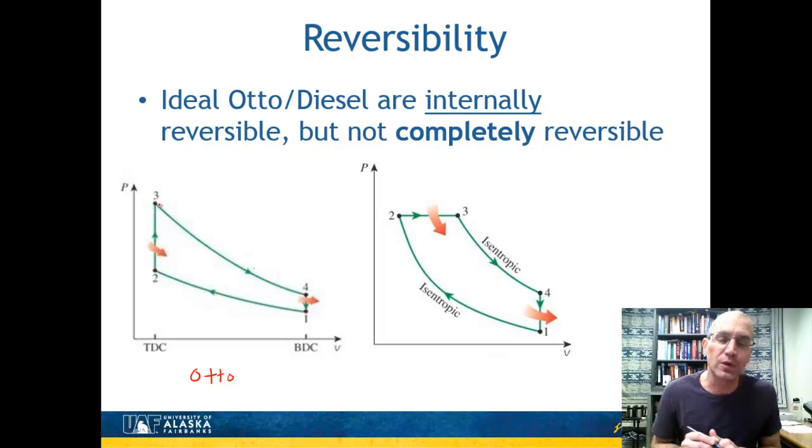However, 2 to 3, that was during the spark ignition. What was happening is the volume didn't change, the pressure increased, and that means that the temperature also increased as we move through here. So point 2 going to point 3, we were at some moderate temperature up to a very high temperature. Now, in order for that heat transfer to happen, we had burning fuel that was at some temperature, TH, that was actually greater than the temperature all along those points. And at each point, energy went from that TH down to here to raise the temperature to that point, to that point, to that point.